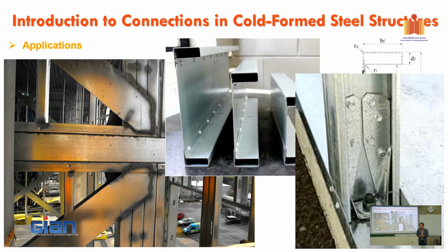For limited thickness, limited for cold form steel. For welding, as far as I understand, is there no limit? You mean the minimum limit? Yeah, in the standard, it doesn't have any minimum. You can weld it to 0.4 or 0.475 millimeter thickness for cold form.